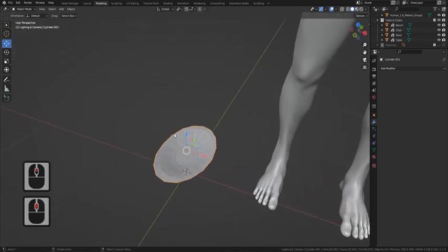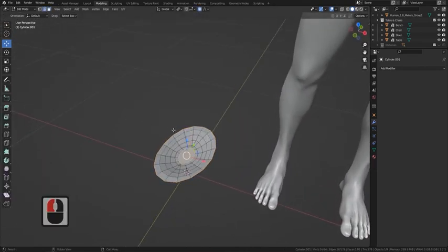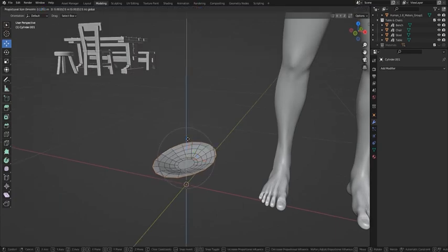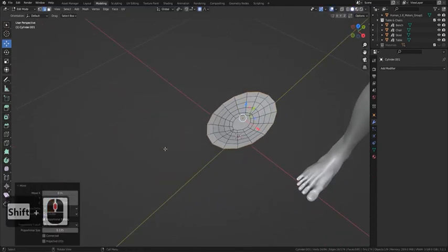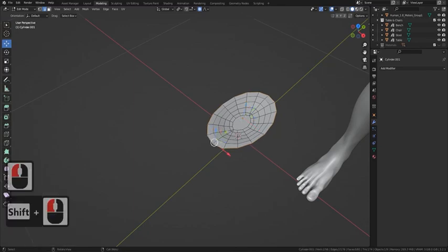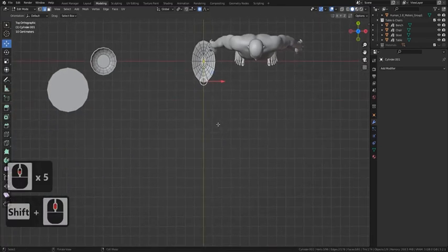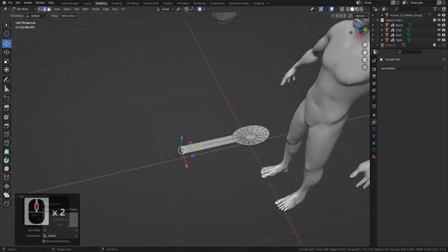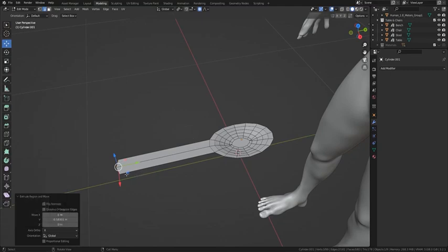All right, finally then, what I want to do is I just want to bring out the edge. So Alt, Shift, and click, bring up just the edge, like so. And now I want to make the actual spoon come out. So I'm going to grab the backs of these, press 7, and I'm just going to extrude it back now. So E and Y, pull it back like so, and that's it. Just a simple spoon. I even like how this edge is coming out here.